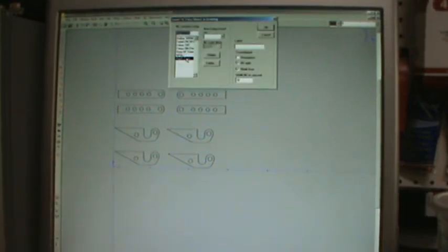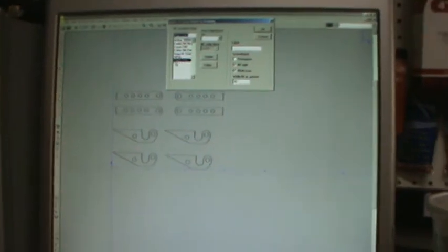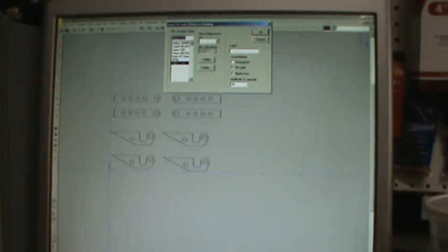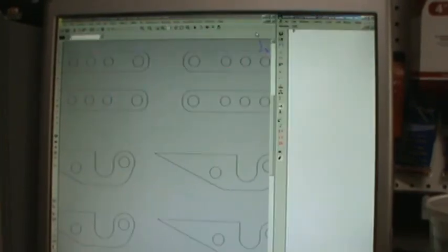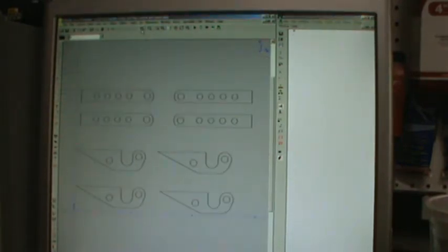Click that. Under NC machine setup, you'll have a bunch of things in here. These are post processors. You want to download the Mach 3 mill post processor off Bobcat's website in this case, and then select Mach 3 mill, and then click on OK, and it opens up the CAM side of Bobcat CAM. So we'll hit the little magnifying glass with the A, which gives it your actual size. It just kind of fills it up, and away we go.